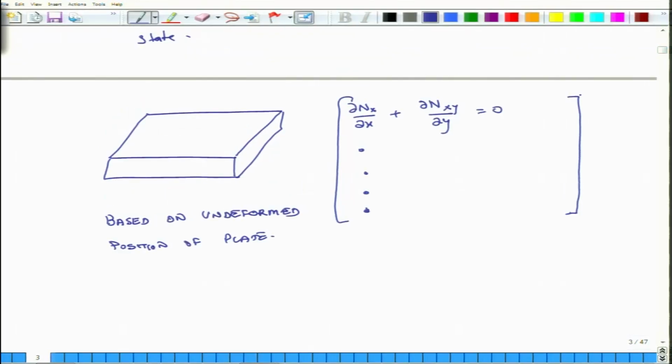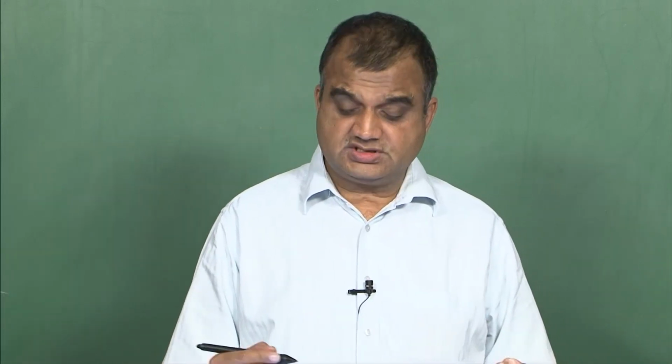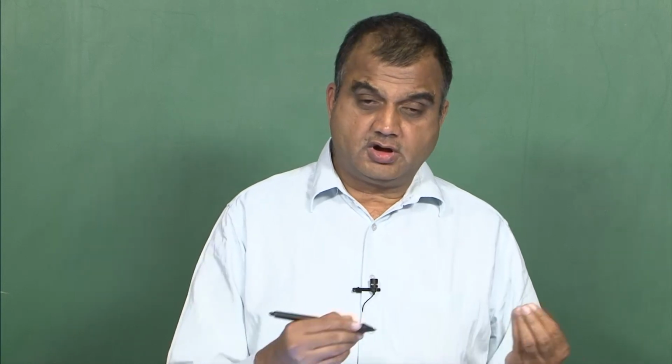We assumed that the deformed position and the undeformed position are virtually the same, because we said that the displacements are so small that the undeformed position and the deformed position are virtually the same. So, we thought internally, and I had not explained it, but this is what was implied, that the governing differential equations for equilibrium for deformed position and undeformed position would be almost identical.